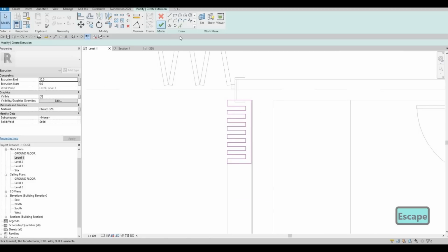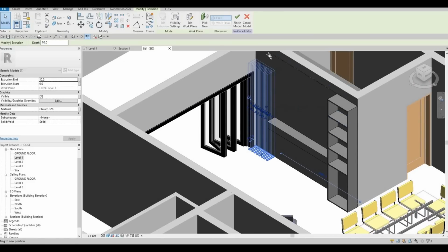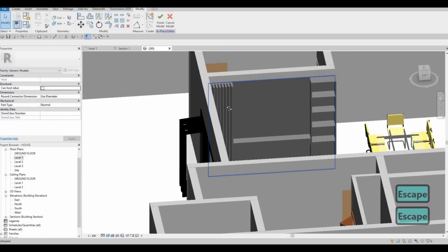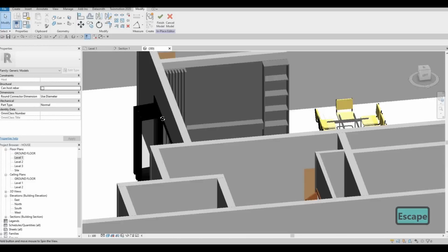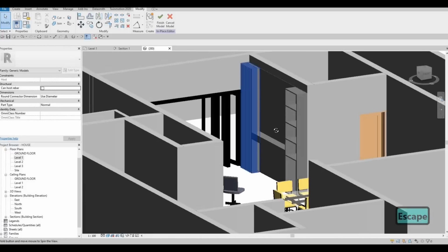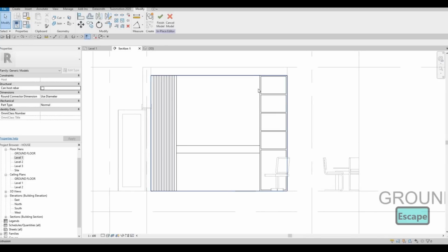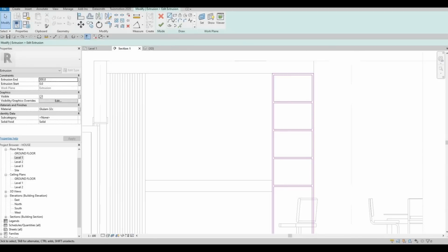And then click on finish, and then go to 3D in order for it to be shown properly, and we could just move it all the way there. So now, simple extrusion will give us this nice entertainment system like this. We can make it further and make it nice. I'm going to have something on this side now. I'm going to create it similar to this.